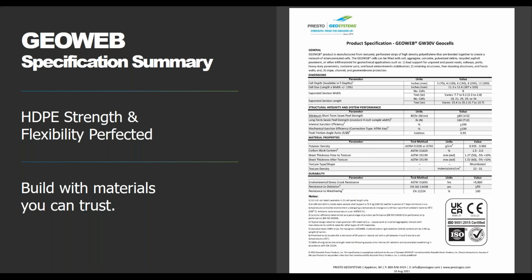Okay, so in order for the GeoCell system to perform uniformly, I'm going to keep saying that word, it's going to be critical that both the factory welded junctions, those internal junctions, the seams that I talked about, and also the field joined junctions that connect individual panels, which are a sort of mechanical junction, perform at the same level as the cell walls.